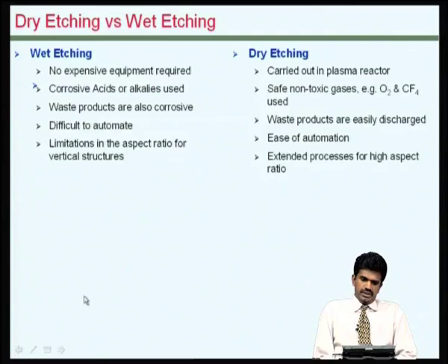Compared to wet etching, this kind of dry etching is usually far more expensive. We need to carry out these reactions in a plasma reactor, which is obviously at a low pressure, and hence all the additional equipment required for that purpose.